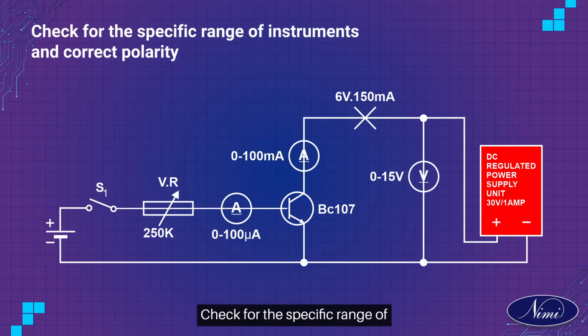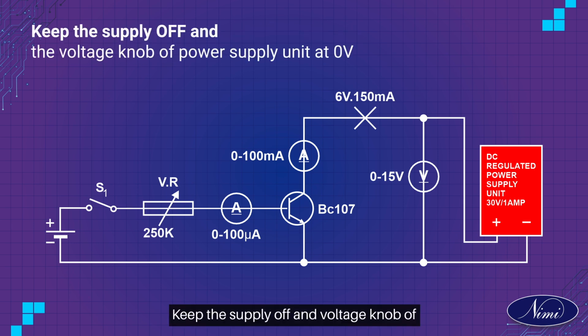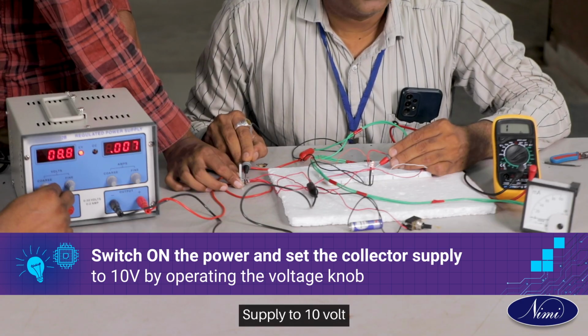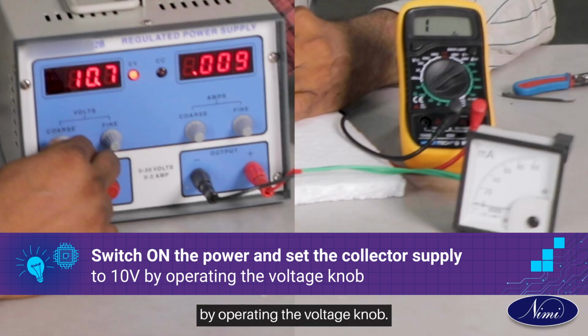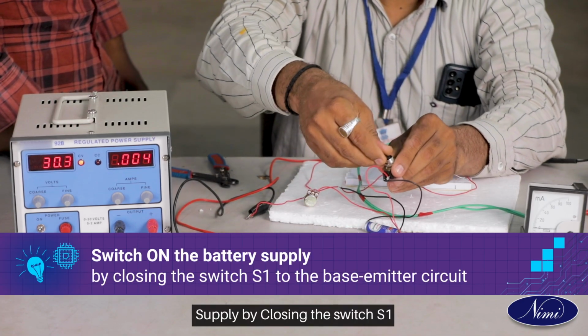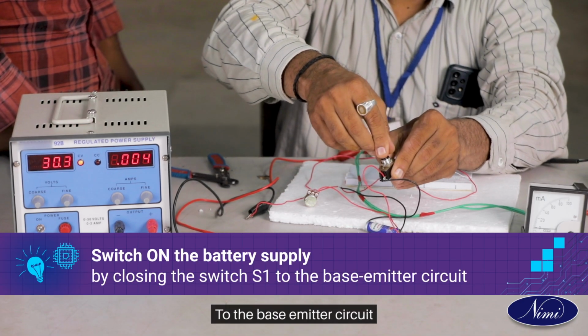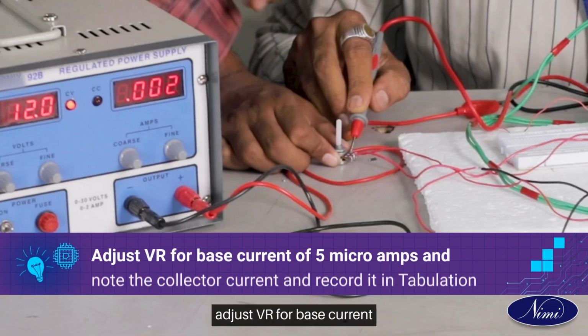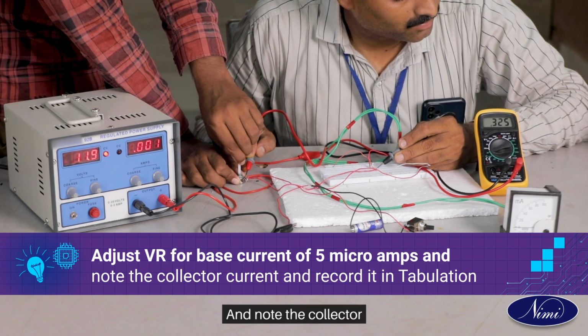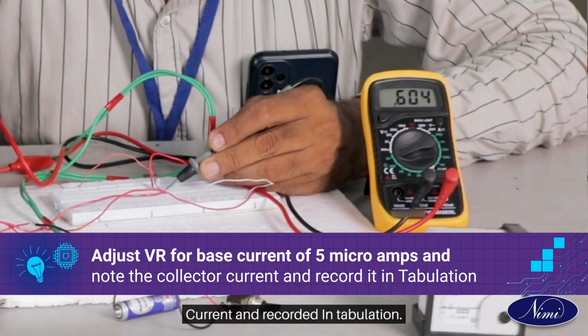Check for the specific range of instruments and correct polarity. Keep the supply off and voltage knob of power supply unit at 0 volt. Switch on the power and set the collector supply to 10 volt by operating the voltage knob. Switch on the battery supply by closing the switch S1 to the base emitter circuit. Adjust VR for base current of 5 microamperes and note the collector current and record it in tabulation.